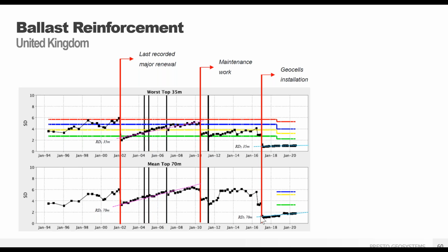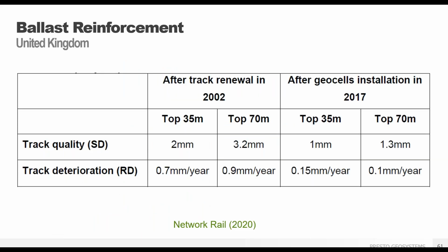Starting in 2018, we put the GeoWeb in. You can see pretty much a linear progression of that degradation. And that has not degraded anymore since the last values that we got in 2020. So very successful installation, and no tamping has been required.